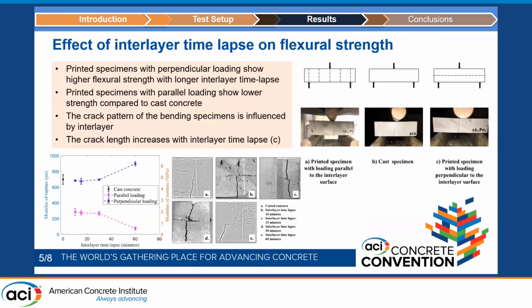For the flexural strength, I also used a parallel loaded specimen and a perpendicularly loaded specimen for printed concrete. For the parallel loaded specimen, logically, it has way lower strength compared to cast concrete, but that's not really the case for the perpendicularly loaded specimen.